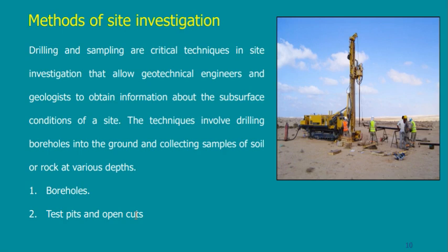But what is the problem of that? The problem is that I cannot drill 100 meters. I will just drill 2 or 3 meters. So I will be limited to a certain depth. I cannot exceed. So this is a problem for me. But I can mix. I can use boreholes and test pits together.